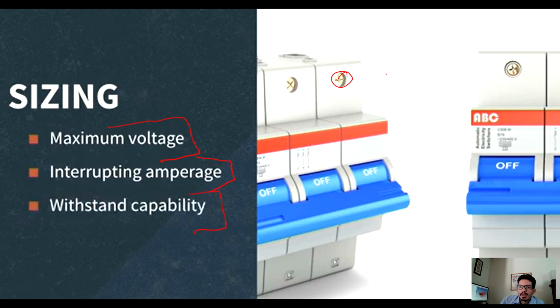Once you choose your breaker, you would have a coworker or your manager or somebody else check for you. Usually you have multiple people, minimum two. One will be shutting down the panel board or doing the tag out, and another person would be working on the breaker box. This is to make sure that the same person is not doing everything, to avoid errors and mistakes and accidents.